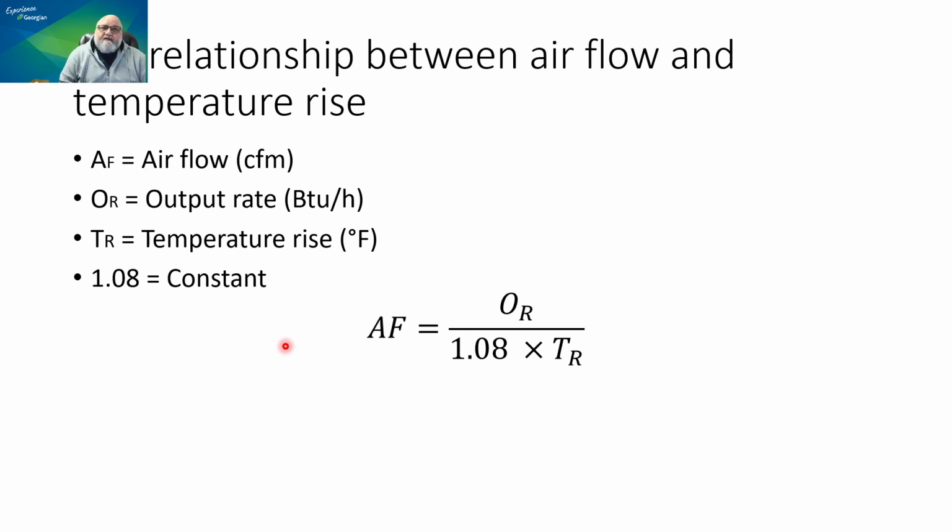Let me give you an example. A customer says the furnace is working, but the room temperature is not reaching the set point. It is -20 outside. They set the room temperature to, for example, 21 degrees Celsius, and the furnace is periodically running and stopping, but it is not going over 18 degrees. And this is something recent. The furnace has been working for 8 years and there was no problem, right? So why is it suddenly not reaching the set point?